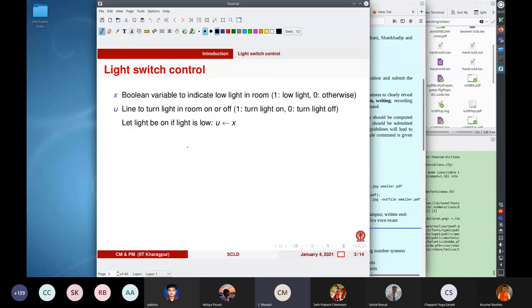Now what is the range of the voltage? We'll just assume that it is between 0 and 5. But again, let me tell you that the reason I'm making this assumption is because the switches, the IC chips, that you have in the laboratory work in that voltage range.